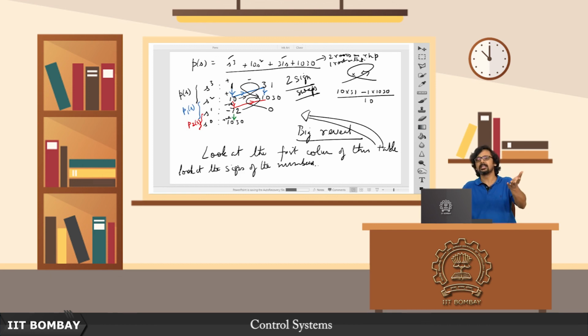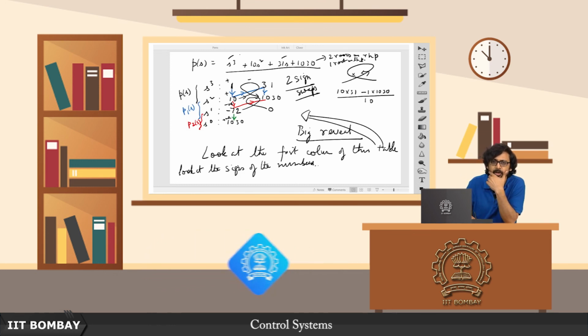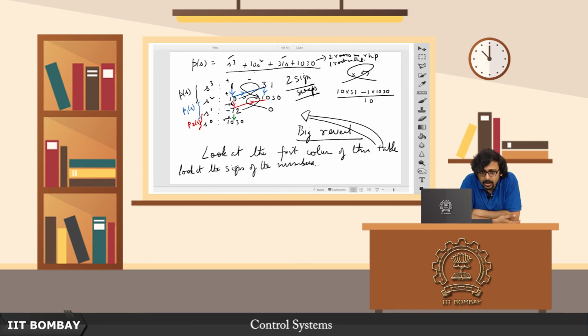Maybe we will give you some ideas about why this is true based on what is discussed in that paper, but that is all for next time, for the next lecture. So hopefully you now have a basic idea of how to construct a Routh array given any polynomial. Maybe we will take up a few more examples in the next lecture to make this clearer, but at least I hope that you are in a position to appreciate why this argument and this logic, or this algorithm of reducing the degree of the polynomial successively to conclude about the roots or the number of roots on the left half plane, actually works.